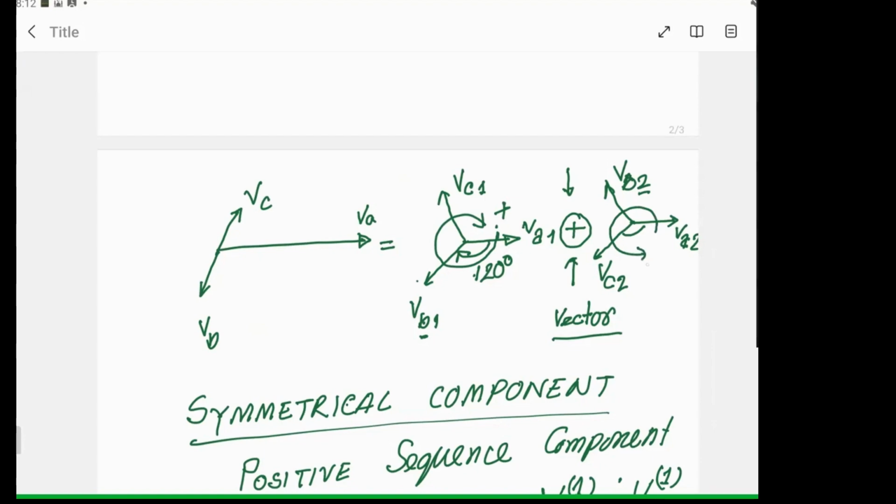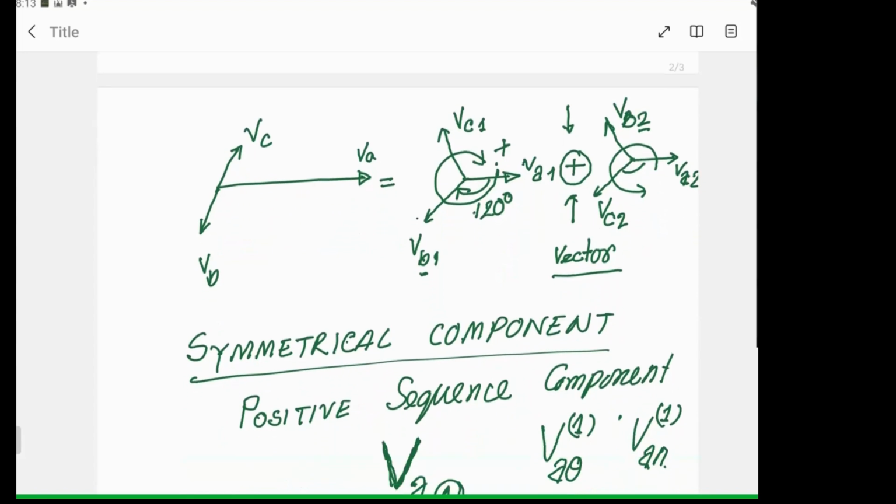That's why it is called the negative sequence. It is just the opposite way you can find the phase sequence. For phase sequence A, B, C, you can find ABC, but you have to rotate in the opposite direction. That means whenever you have a fault, this particular magnetic field is produced in the opposite direction, and you have to add another quantity.